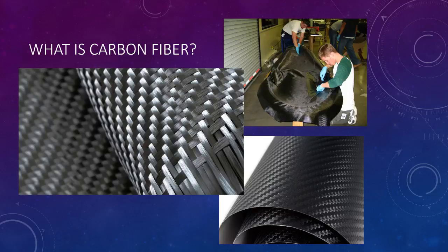Carbon fiber is basically very thin strands of carbon, even thinner than human hair. These strands are twisted together like yarn and woven into a cloth form. The carbon fiber is then laid over a mold and coated with stiff resin to create the designer's desired shape. The process is very similar to that of paper mache.